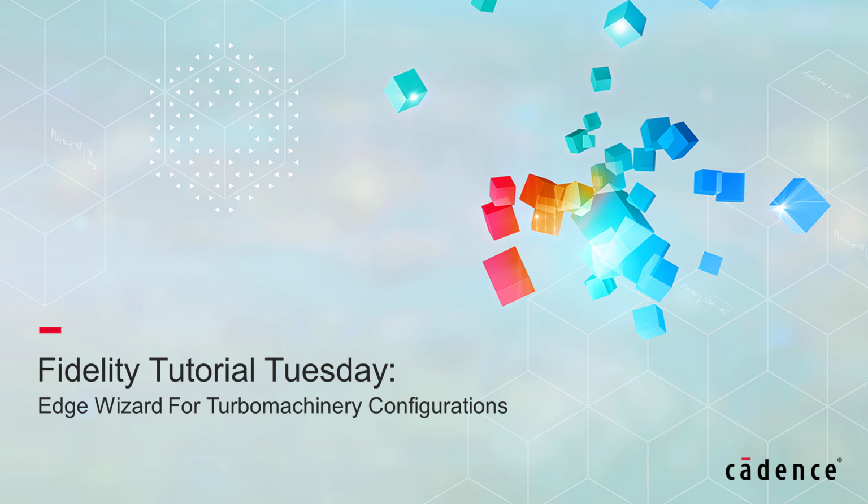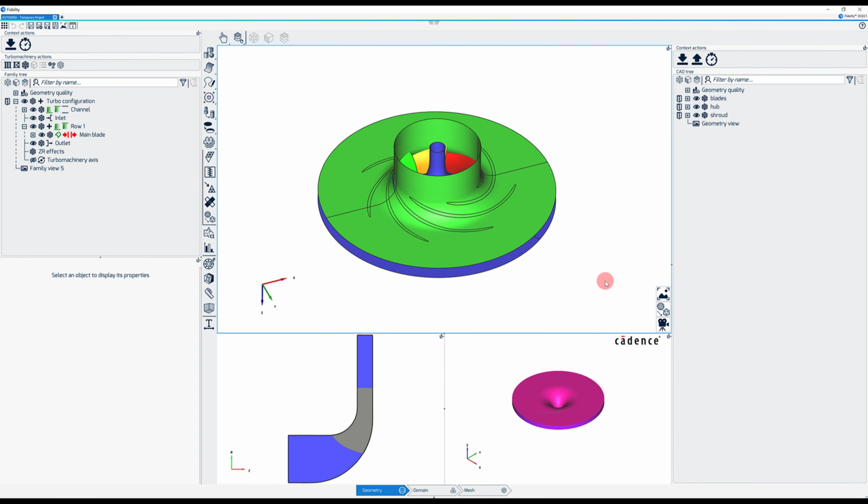In this video, I will cover the main features linked to the Edge Wizard for Turbomachinery configurations. The Edge Wizard is a new feature included in the AutoGrid template of Fidelity, which allows to define or redefine blades' leading and trailing edge curves for turbomachinery meshes.